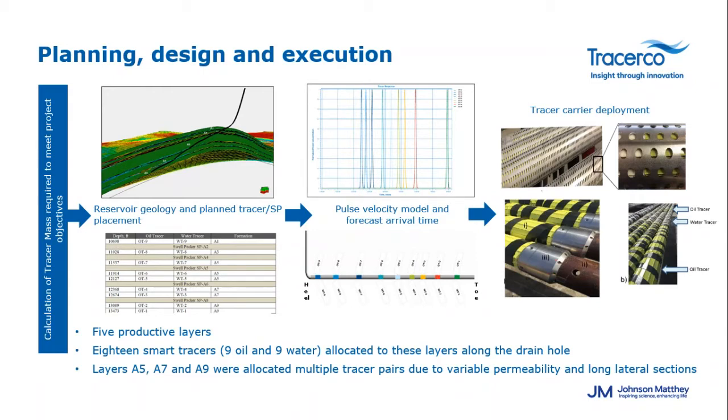Due to a larger number of tracers available than zones produced, several zones were broken into multiple sections. This created more definition along the wellbore and more comprehensive information to compare to log data. Based on the expected volumes and the wellbore design, the sampling timing was forecasted to ensure the transient tested would be successful. The tracer masses were calculated to meet project timing goals and then applied to the base pipe and covered with screens.